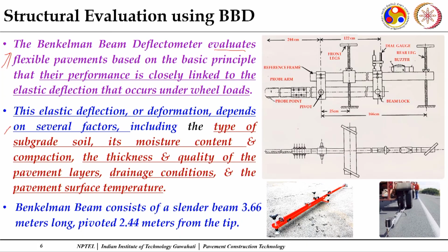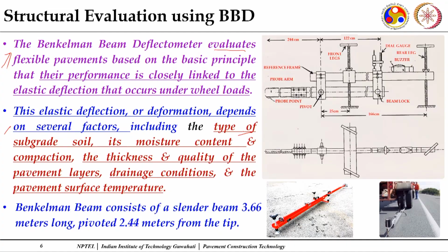This elastic deflection or deformation depends upon several factors. If you have a pavement composition and a load is applied, some deformation will be there, and it will depend upon several factors of the pavement. What are those? First of all, the type of subgrade soil, the subgrade over which the entire pavement crust is resting. So, it will depend upon the subgrade soil, its moisture content, what the state of it is, and its compaction, how well it is compacted.